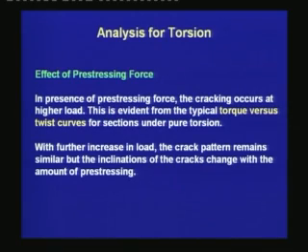Next, let us understand the effect of prestressing force. In presence of prestressing force, the cracking occurs at higher load. This is evident from the typical torque versus twist curves for section under pure torsion. With further increase in load, the crack pattern remains similar, but the inclinations of the cracks change with the amount of prestressing.